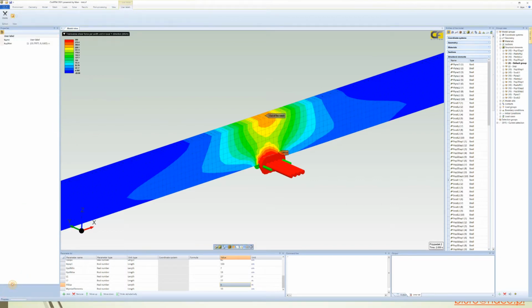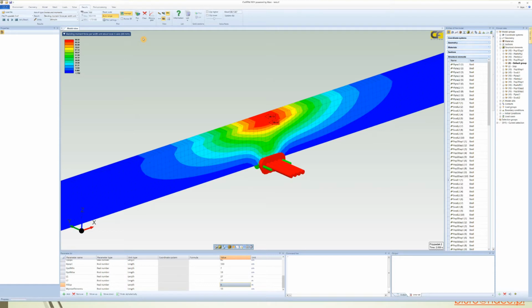Also, apart from plotting and adding different levels for maximum values, a path could be extracted through the section or the height of the elements, and extract those graphs to analyze forces and moments, mainly shear forces and bending moment on the web of this T-beam. Yes, because later we want to see the chart as it happens with beams, in 2D. Here is now the bending moment. Here we're plotting the bending moment with the maximum value on the connection between the flanges and the web.